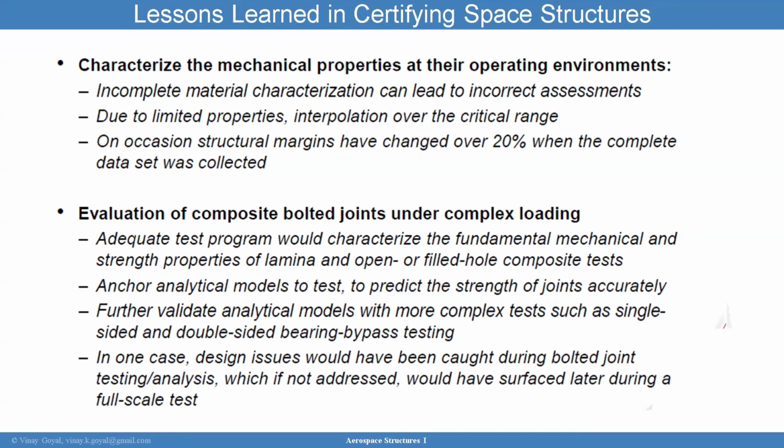Also, in some cases, testing over the full range, while it may seem expensive initially, could actually later on lead to a greater reduction in weight. For example, if the strength in between temperatures for whatever reason was higher, I could take advantage of that.